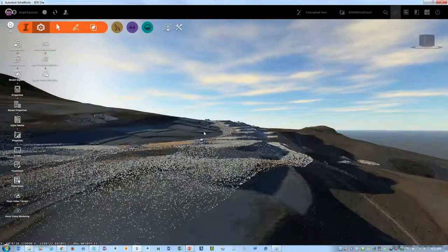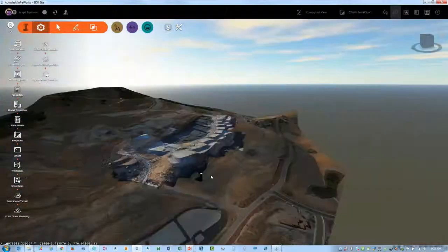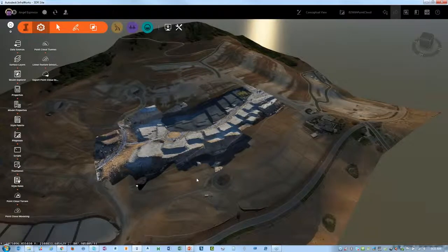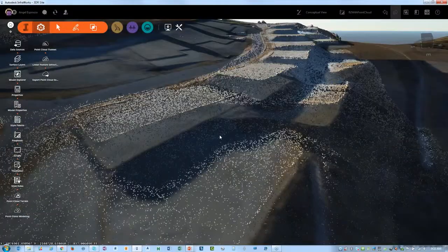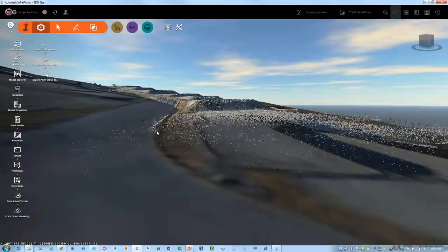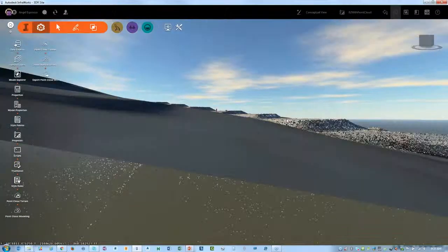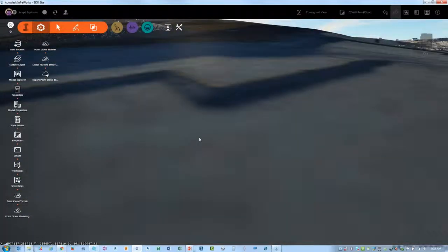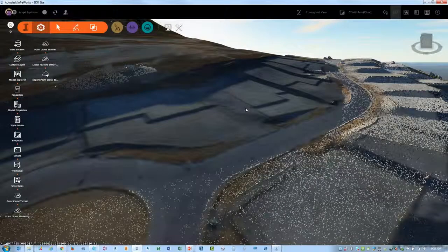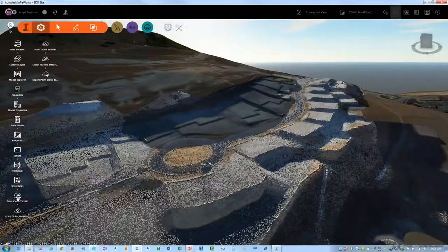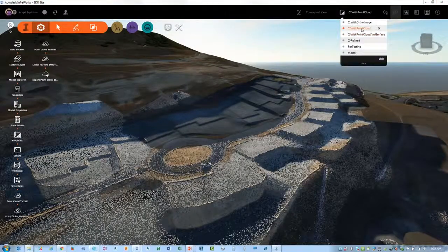Now, in some areas, if I zoom out, it'll look a little bit better. In some areas, this point cloud is above the ground that came in from the USGS. In some areas, that point cloud is below the ground. And I want to be able to push that point cloud into this existing ground that I received from USGS. Absolutely doable. Here, right here, there's the command called point cloud terrain. It doesn't take terribly long, but I've already pre-done that.